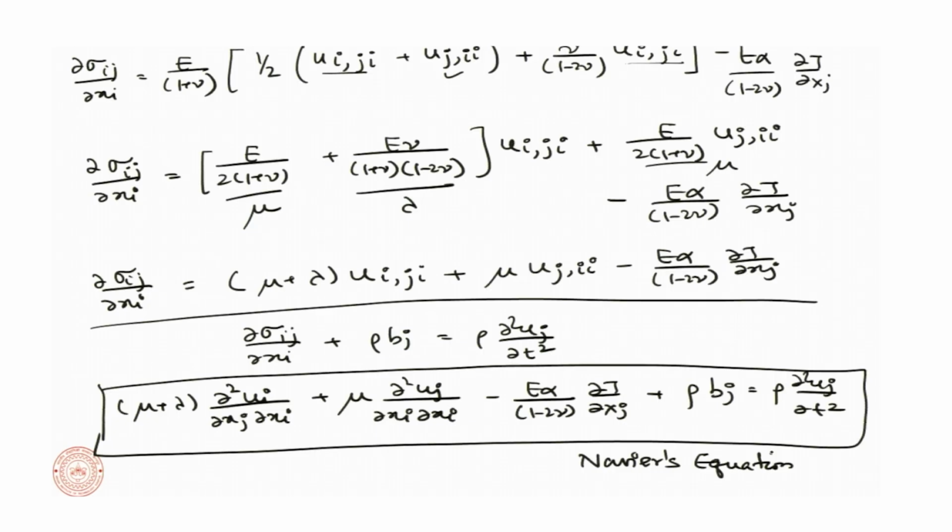So we have seen that all the things we have been doing up to this lecture 4, we are able to combine into one equation. Now this entire expression is driven by these deformation terms. U is everywhere, except we have these two terms. One is this body force. Body force is well known. It can be gravity, it can be due to some electromagnetic effect, it can be pressure on the entire body, and this gradient of temperature is our thermal deformation term. So temperature driven deformations will only cause stress in the body if there is a gradient. That means that the temperature needs to be a differential. It cannot be uniform temperature.